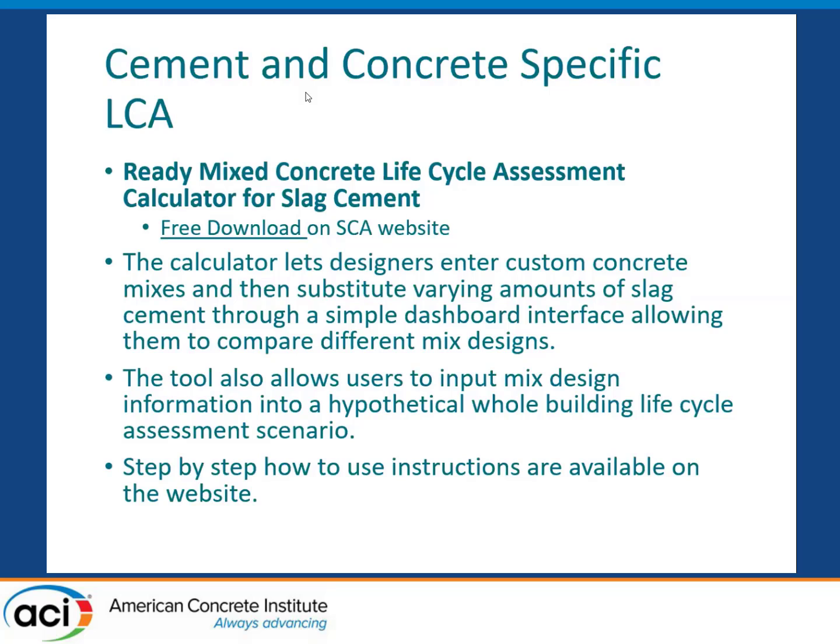Oh, one last thing. When it comes to cement and concrete specific LCAs, we can use the ReadyMix concrete lifecycle assessment calculator that can be downloaded for free from the Slag Cement Association website. The calculator lets designers customize mix designs and then substitute various amounts of slag through a simple dashboard interface, allowing them to compare different mixes.